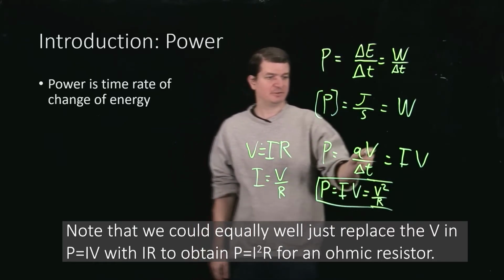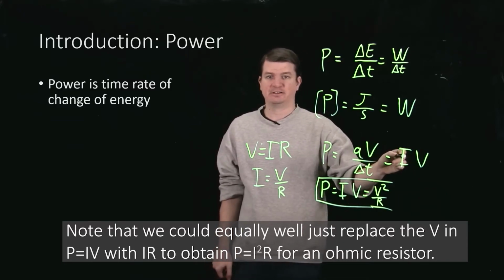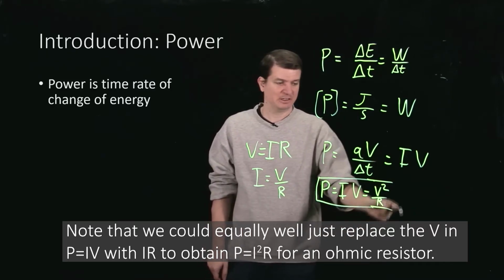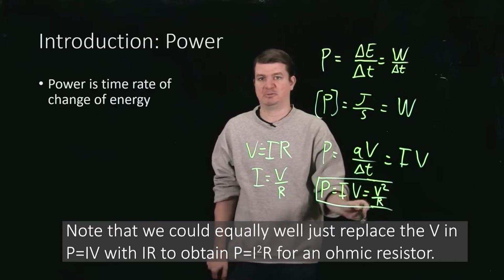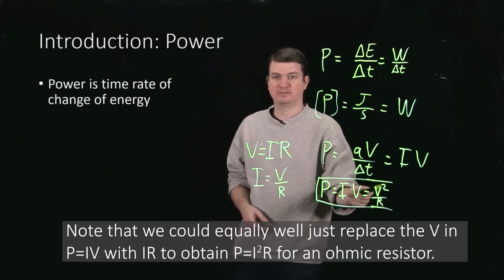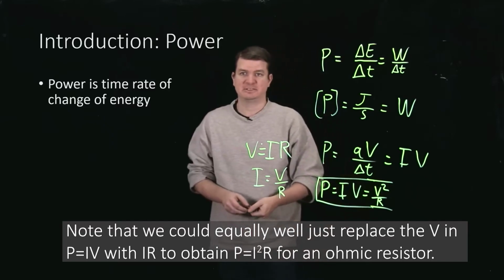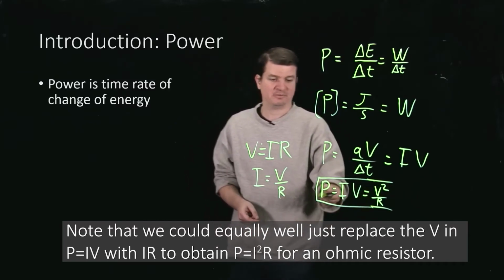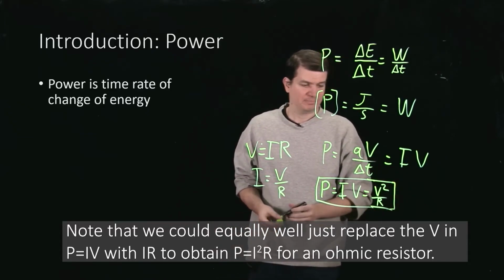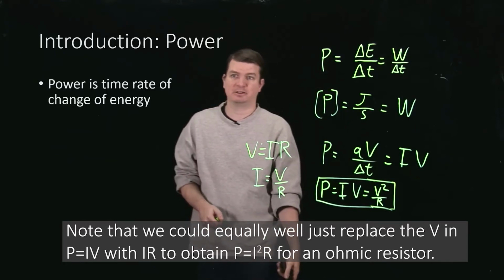So connecting these different ideas, here I'm discharging a capacitor. That resulted in a current. That current, if it's passing over a nice ohmic resistor, is described by V on R. So for the ohmic circuit, I can also talk about the power as just being V squared on R. So the voltage across some resistor squared divided by its resistance gives me this value of the power. Okay? So those are some very important equations, very important forms for thinking about what's going on there with the power.